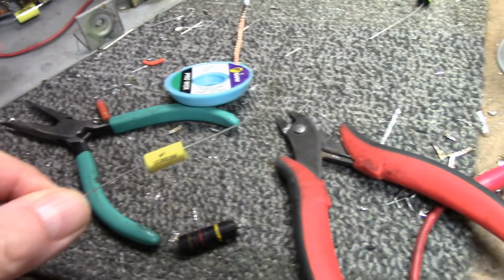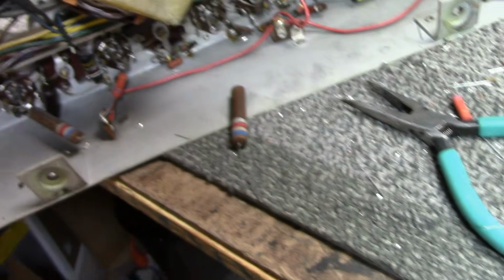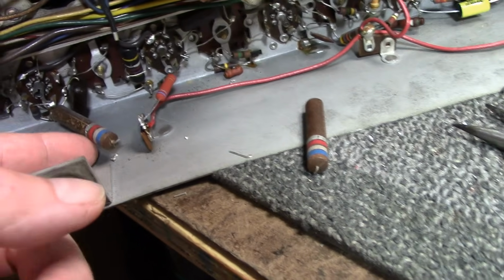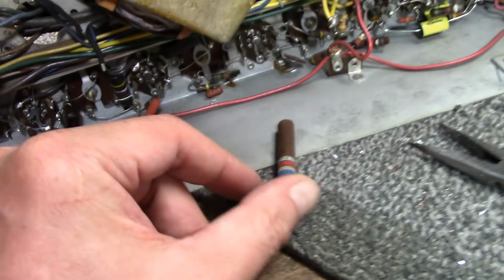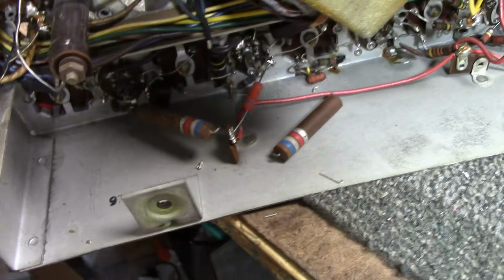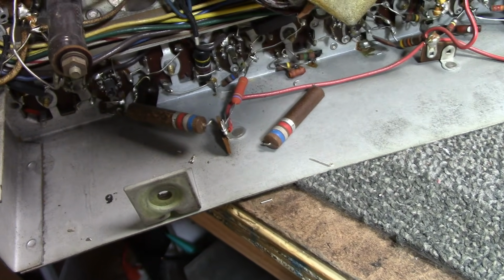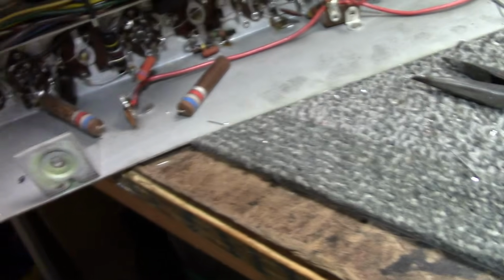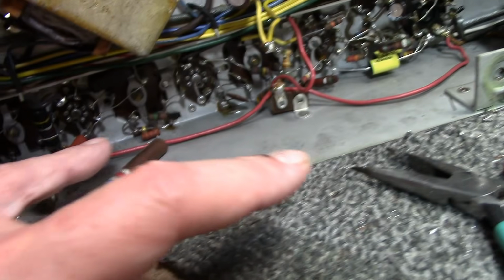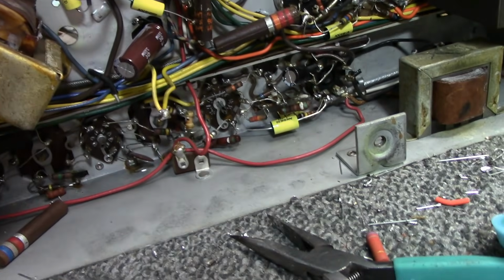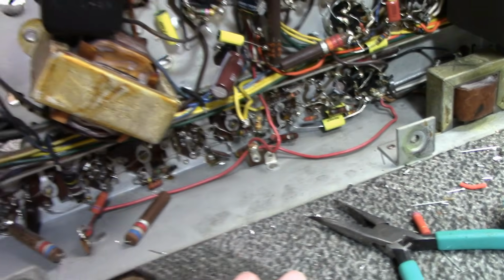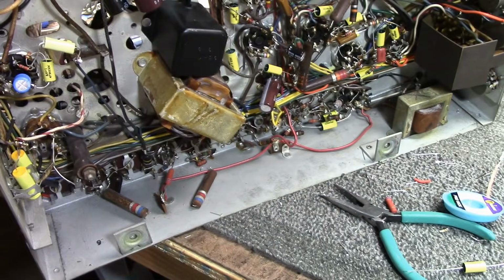I am going to replace them with these guys. And I've been double checking resistors, and some of them are out of spec. For example, there were a couple of these big old 6.8K 2 watters that have drifted pretty far out of tolerance, so I'm working on replacing those. And I'm going to check the rest of these resistors. Once that is done, we will do the sound alignment.